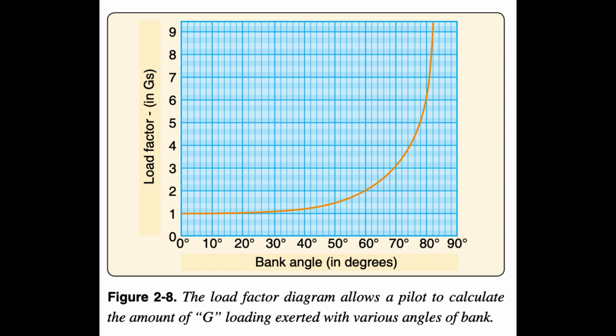The weight of the helicopter can also be influenced by aerodynamic loads. When you bank a helicopter while maintaining a constant altitude, the G load or load factor increases. The load factor is the actual load on the rotor blades at any time, divided by the normal load or gross weight of the helicopter and its contents. Anytime a helicopter flies in a constant altitude curved flight path, the load supported by the rotor blades is greater than the total weight of the helicopter.